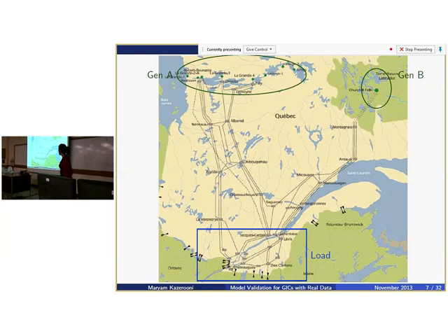This is how the blackout happened. First, three SVCs were tripped, one after the other, because of the high harmonics in the network, which were caused by half-cycle saturation. After losing these SVCs, the network lost a lot of reactive power support, and the voltage went down.